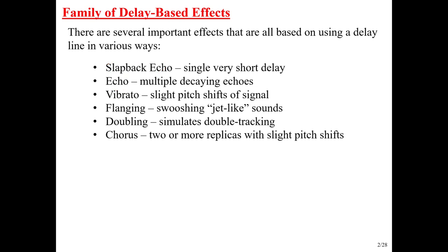Then we get into vibrato and flanging. Those are two things that are based upon delay-based effects. So vibrato gives a shift in the pitch of the signal, just a little bit, makes it kind of wobble around. It's based upon or tries to mimic the idea of what a singer does when they hold a pitch. They just wiggle it around just a little bit in pitch.